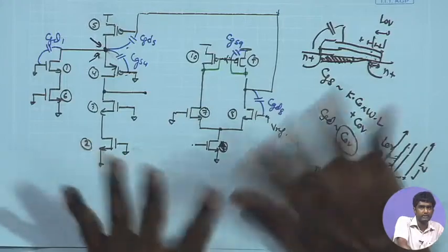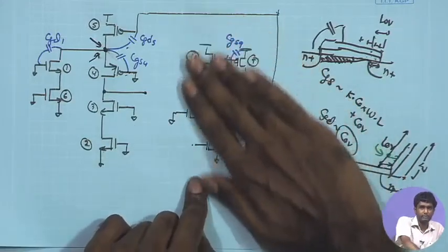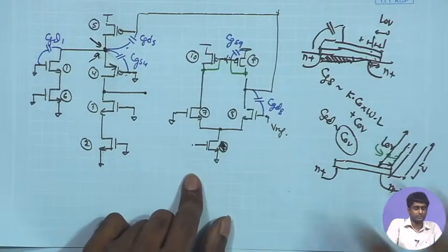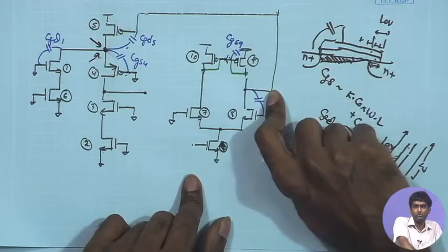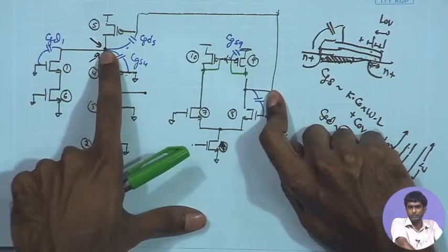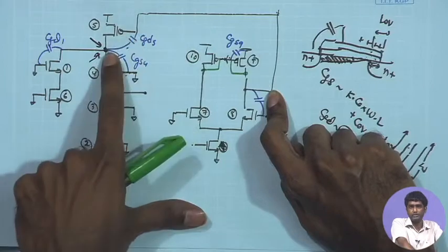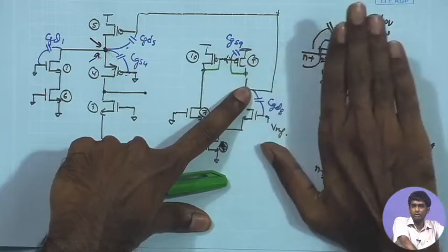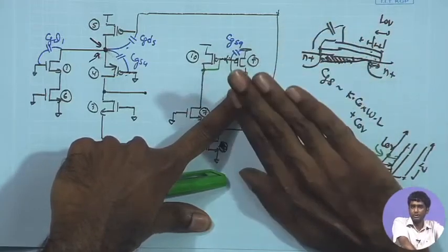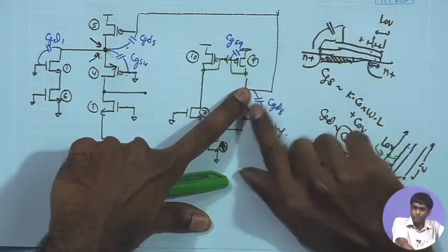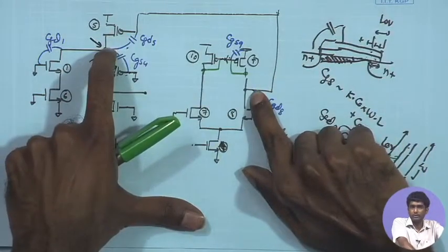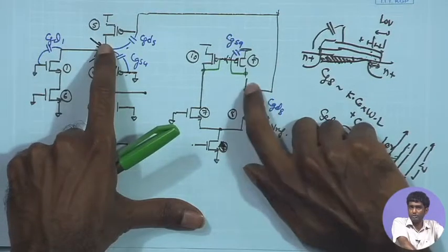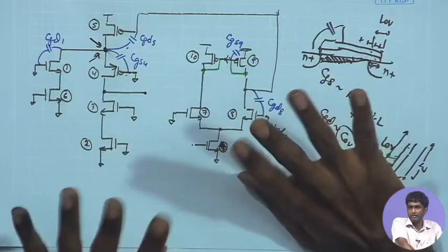So, you have to be aware that whatever design choice you make at one point, for example, for reducing the bias current over here, that can also influence your overall stability, because here again it can bring up a non-dominant pole, which is probably even lower frequency than this one, because it is having a Miller multiplication factor of the CGD5. Along with that, impedance over here is getting closer to RO, and 1 upon GM is no longer much smaller than RO, as we always assume. So, that will push this node even lower than this one, and that will start contributing as a dominant pole. So, rather than this being the non-dominant pole, this will become the non-dominant pole,